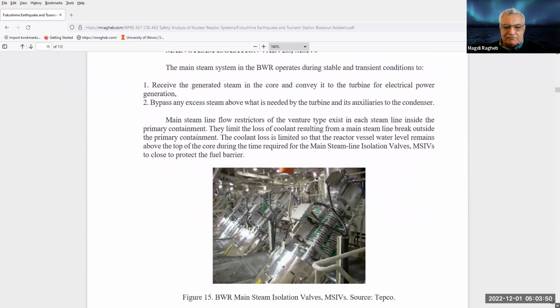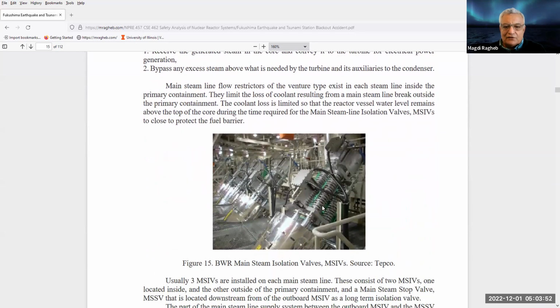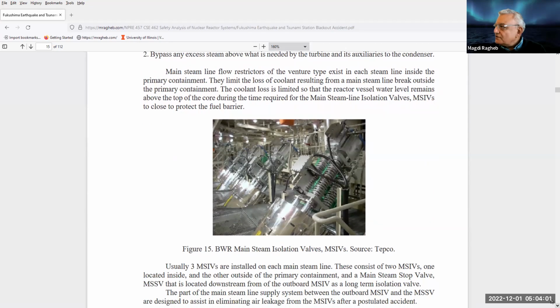The main steam valves played a role in that. The steam valves open up against the pressure of springs, as you could see here, to get the atmosphere of the containment released to the environment in the case of a release of hydrogen. And the hydrogen release, as we identified it, would come from steam at very high temperature from the core spray system in boiling water reactors interacting with a metal. The metal in that case is the cladding, the zirconium.